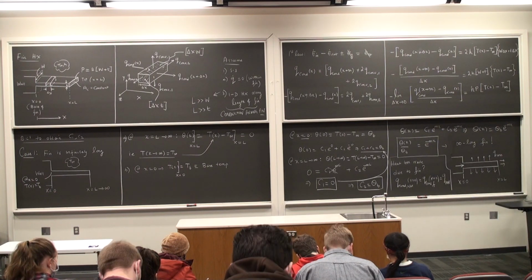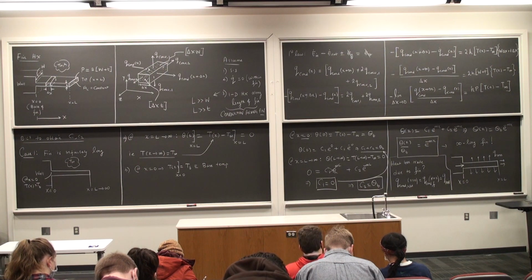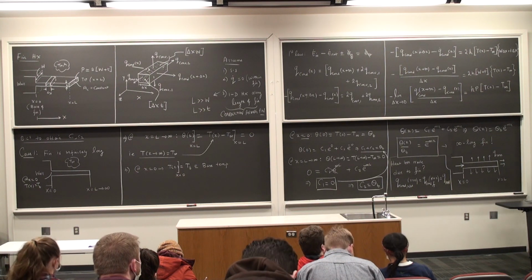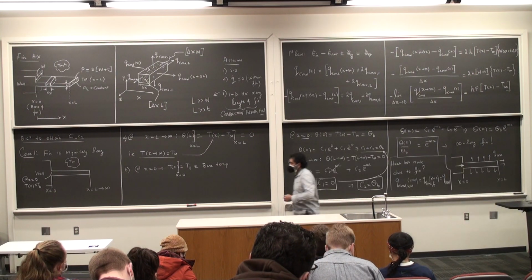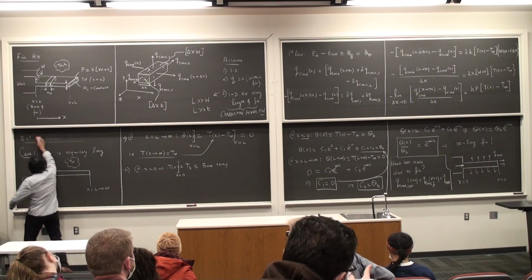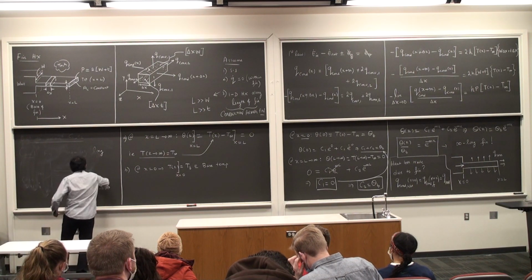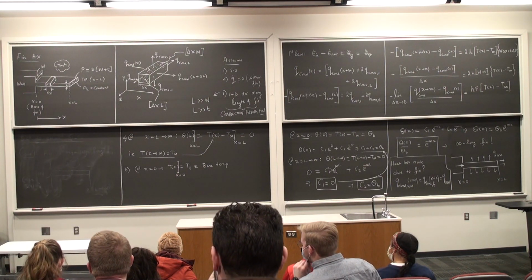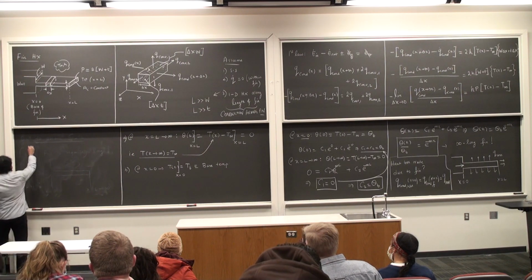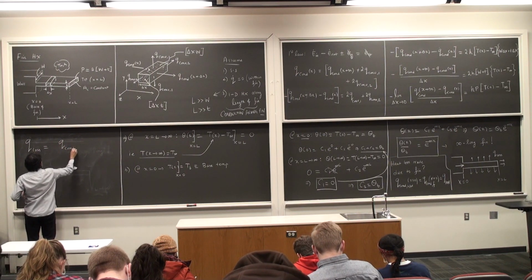And I want to see if this makes sense to everybody. All the heat that is entering the fin has to leave. The damn thing can't be sitting there idle, right? Heat cannot be sitting idle. It has to go somewhere. And so if I make use of this idea, this is now fairly trivial if you look at it. I'm not interested in the wall. I mean, if I'm given information, I might be, but I'm interested in the fin. So Q loss is equal to Q conduction fin